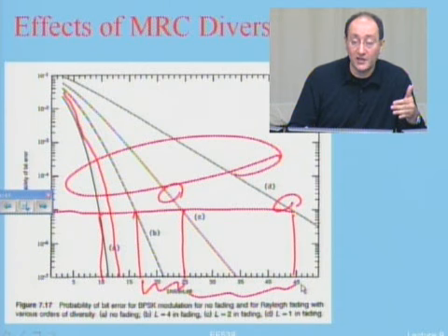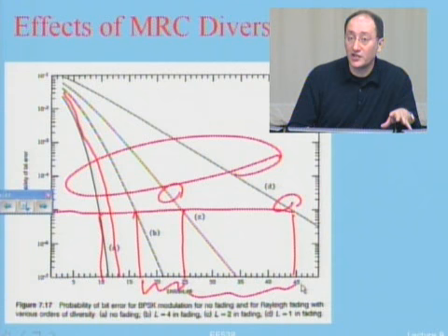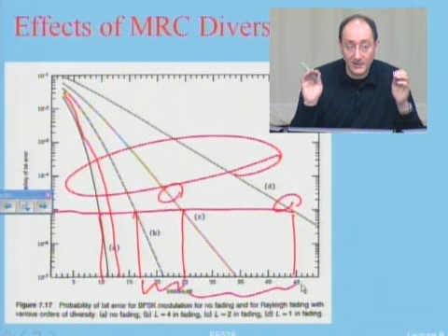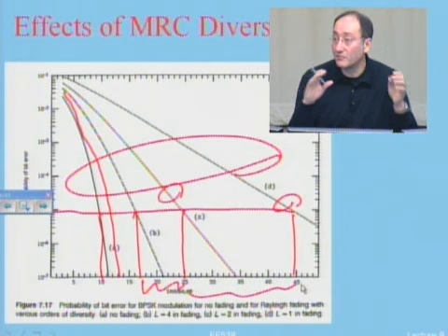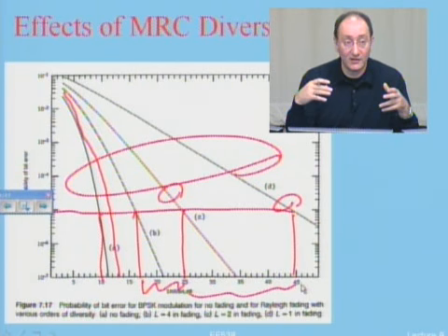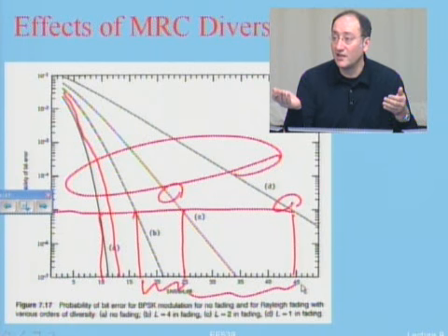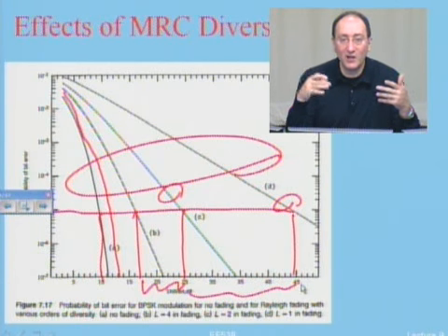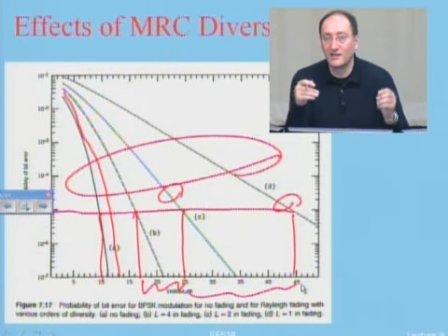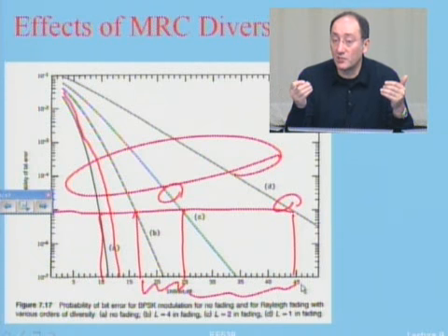Then we talked about space-time coding, in which the bits that I'm transmitting in the antennas at the base station, I shuffle them somehow, and I code them. So I send one bit in this antenna, the other bit in the other antenna. Then next time I repeat the past one in the first one. So somehow, when I'm out of fade, I have some bits. That's the so-called concept behind space-time coding.